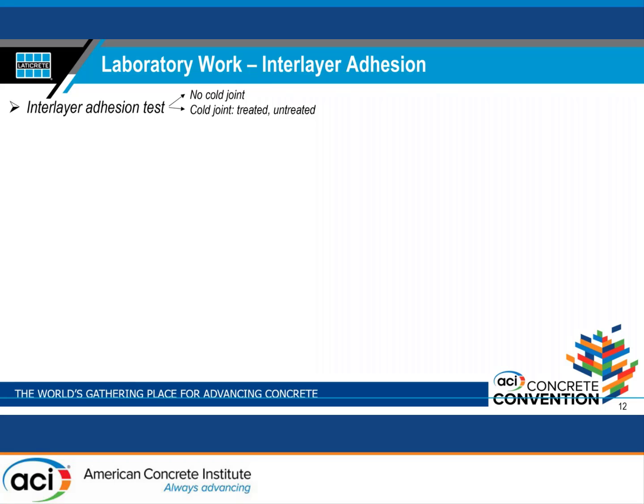The cold joint is a plane of weakness in concrete caused by an interruption or delay in the printing. It occurs when the first batch of concrete has begun to set before the next batch is printed on top of it, so that the two batches do not intermix.